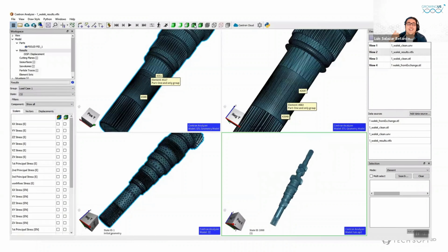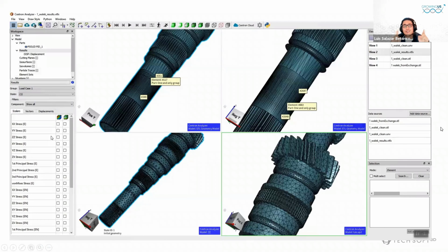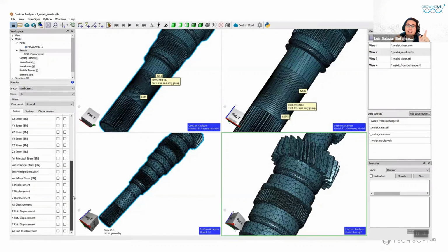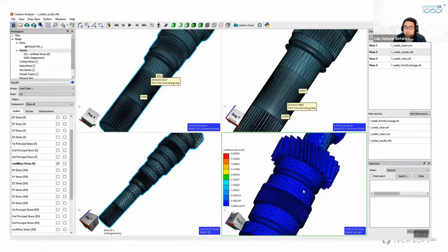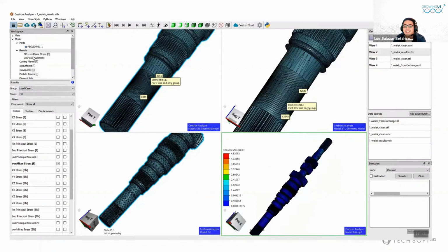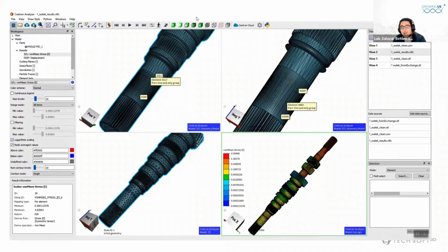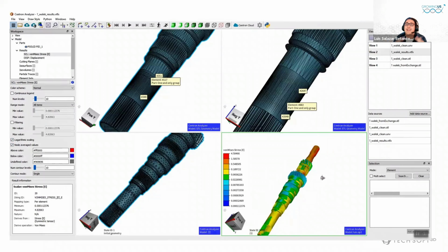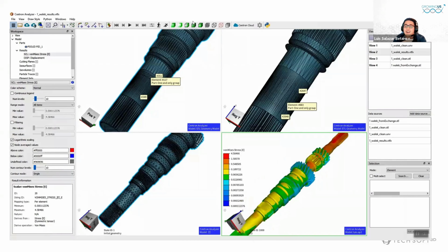But let's move to another product that we can offer, which is the solving part. And let's put some numbers into those results. By using another amazing product from Visual Kinematics, let's make a finite element simulation and let's display the displacement and the stresses. And we are finally getting to that result here, where I will show you the von Mises stress in a logarithmic scale, removing the mesh to see some nice color. We see here the full complete pipeline from the CAD file into the final result.